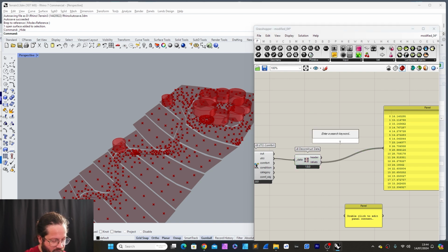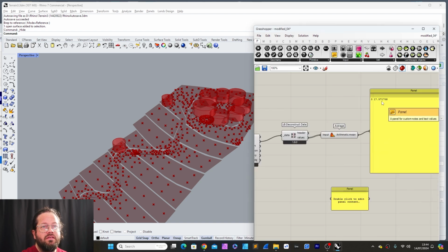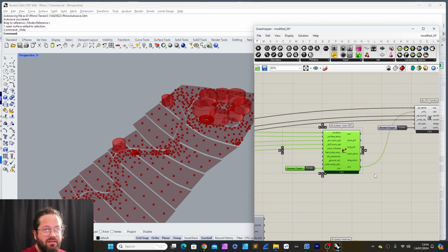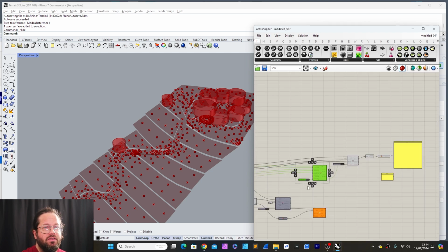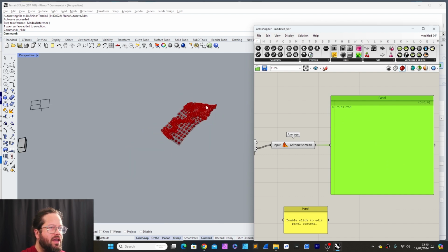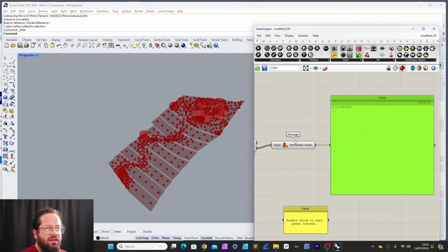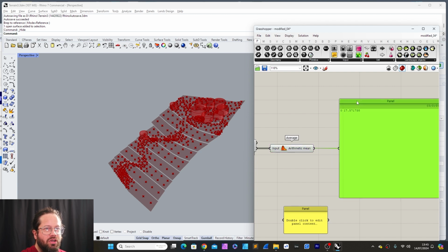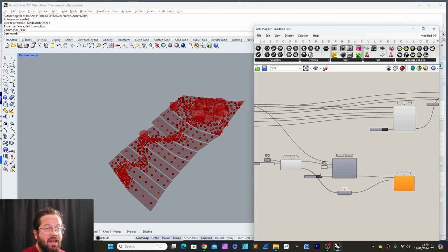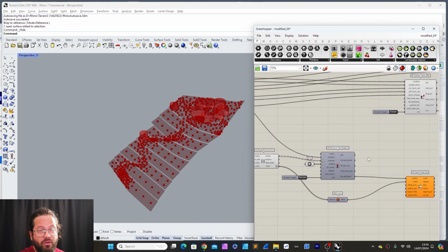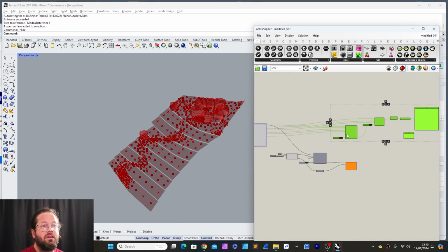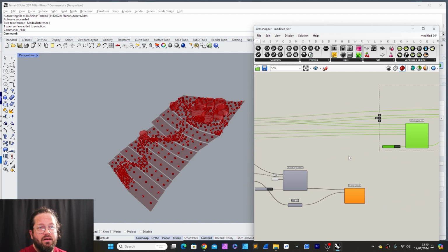So if I say, for example, average, the average value is 17. Now this actually has changed because we added this mean radiant temperature. We didn't use that before. It's quite interesting. That actually had a bit of influence on the output. But imagine we would now test this site, each point, the average per year, the average outdoor comfort might not change much. So where this actually makes much more sense is to test the outdoor comfort in a specific time of the year. And what we could do is limit the data to a specific time.